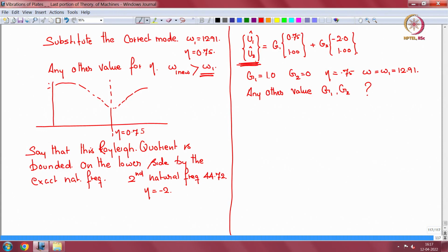Now let us see, if we substitute this into my Vm and psi m from above, I get for Vm 1/2 into 100 into 0.75 g1 minus 2 g2 whole squared, plus 1/2 into 200 into 0.75 g1 minus 2 g2 minus g1 plus g2 whole squared,